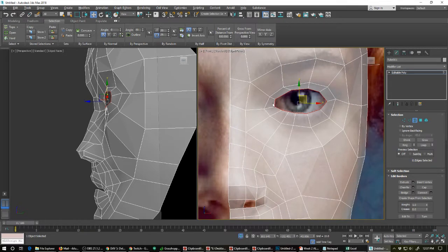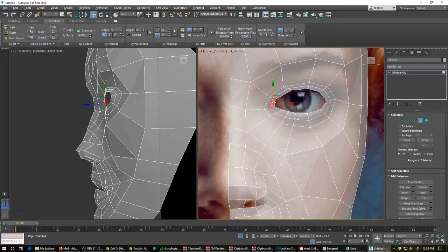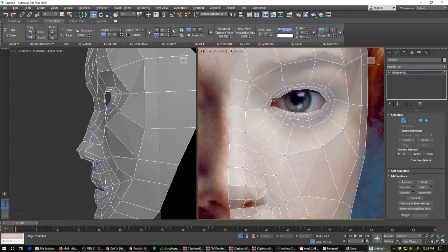I'm going to grab this and ring that, connect it once, and slightly pull it out. That's going to give me my lip for my loop here, and also a plane here. So I'll go in, select the four, and hit delete. That gives me some edges to work with, so I'll grab these and start pulling these down. I can add more geometry down the road.